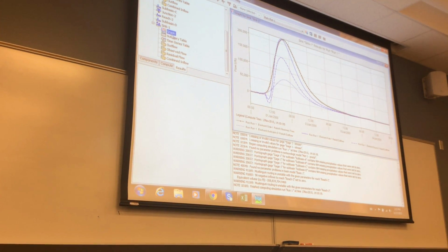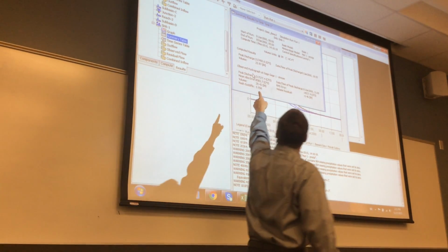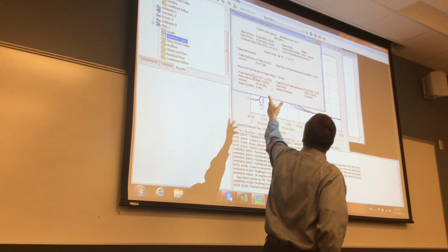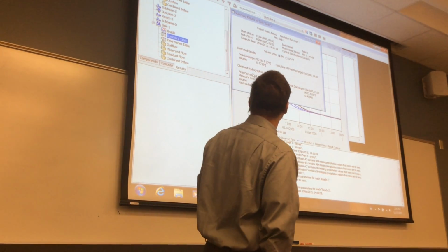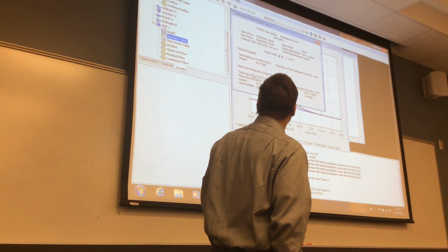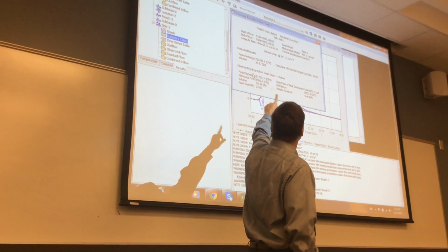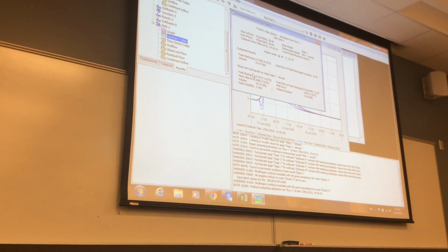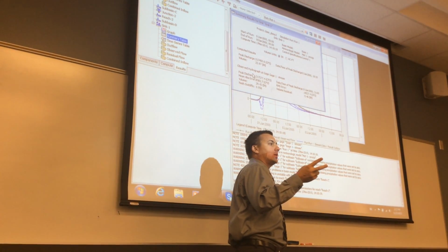Now if I look at my summary table, it should tell us the peak discharge: peak discharge for my computed results, and peak discharge from my observed hydrograph. I guess I guessed really well at these curve numbers, because I've never seen this work so well. If you wrote that down, that's a good one to go with. It's also giving you some error statistics between the two. The next step here is to calibrate our model, which means we want to make sure that the blue line matches the black line.